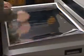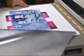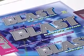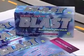After cooling to the touch on the laminator table, the silver support layer is peeled away from the intermediate and discarded. The Kodak Approval proof is now complete. The proof can be viewed and used immediately or can be further prepared to yield a three-dimensional package design proof.